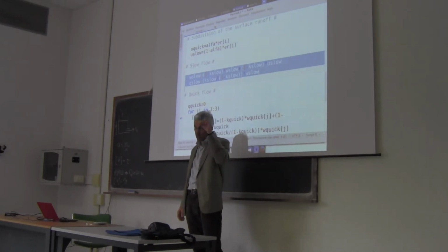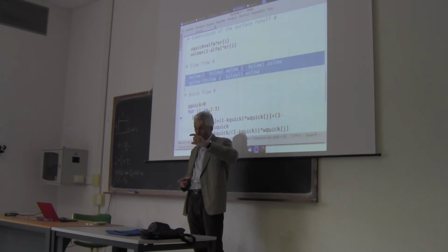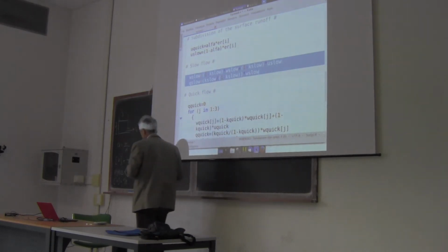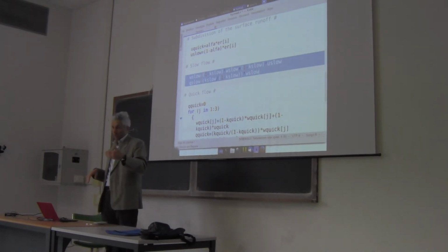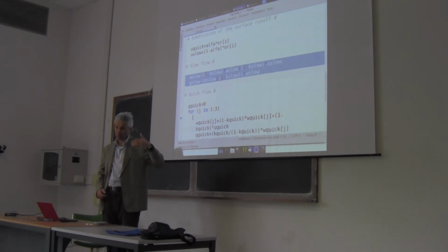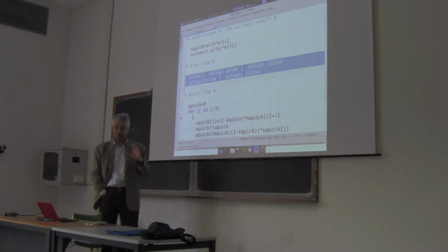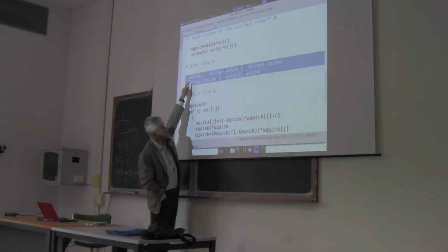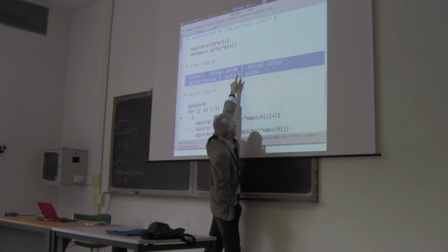It happens that U slow goes into the linear reservoir, the only one, and then we have to update the volume contained in the only one reservoir by adding U slow. And then, after updating the volume, we need to compute the outflow from the unique reservoir. It's very simple in principle, because we need to keep the previous value of W slow, and we computed it through the conversion factor at the beginning, which was a conversion factor that we recognized was probably a bit too correct. Okay, and in fact you see here that W slow is updated by adding to the previous value, which is here, U slow.